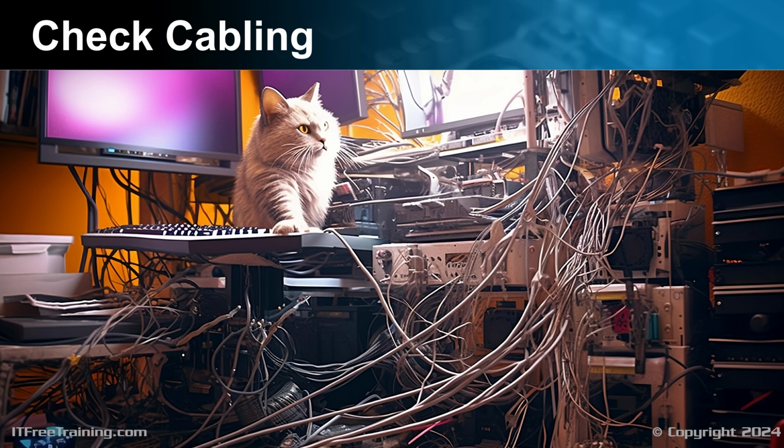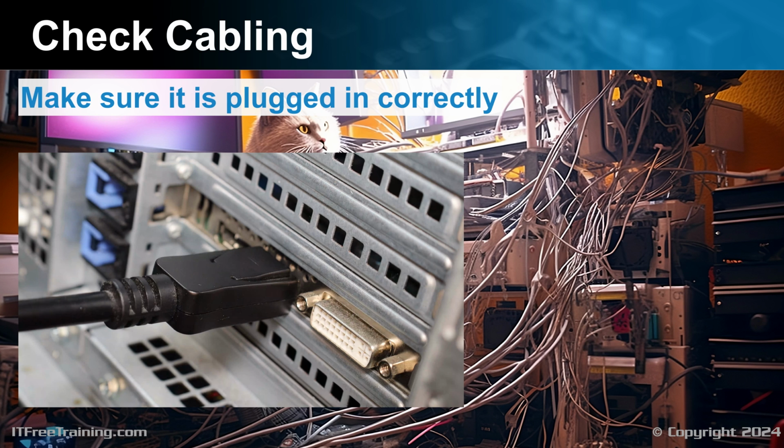One of the initial steps is to thoroughly check all the cables. Often, a loose connection is the simple cause of the problem. Ensure that every cable is securely and properly connected. Double-check each connection for a firm and complete fit to eliminate any potential loose or partially connected cables, which can often be the root cause of such issues.